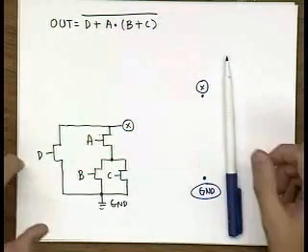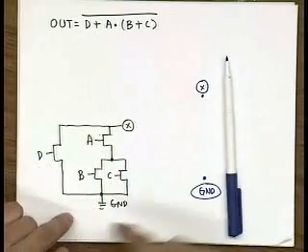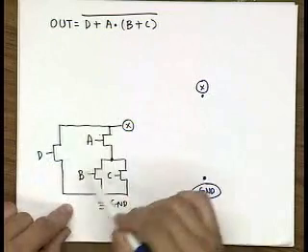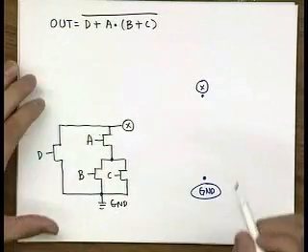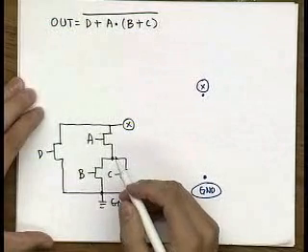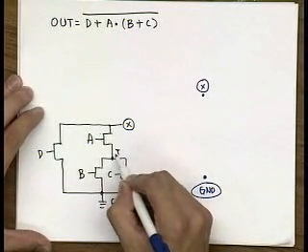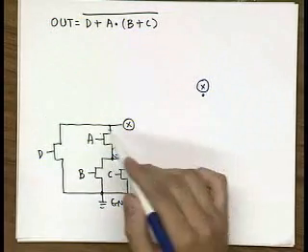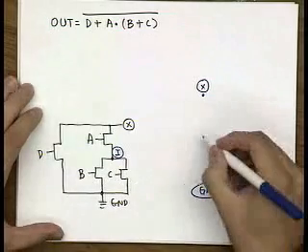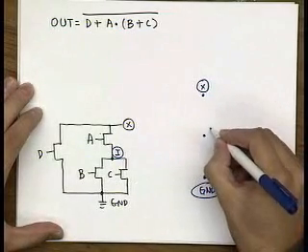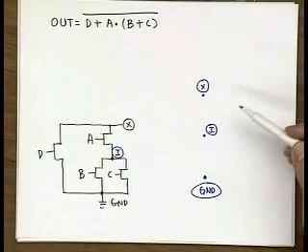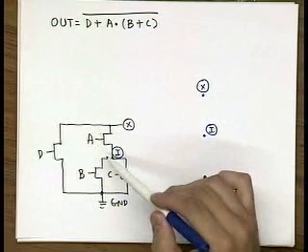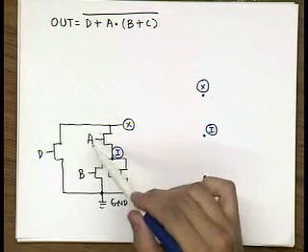And all we need to do is basically to find an equivalent representation of this circuit such that we can connect this X and ground, depending on the topology of this circuit. Let's introduce one more intermediate node here and call it I. So basically, step number 1, you label all the nodes in your circuit. These nodes become nodes in your graph over here. And now you connect all these nodes using labeled edges that correspond to your gate signals.